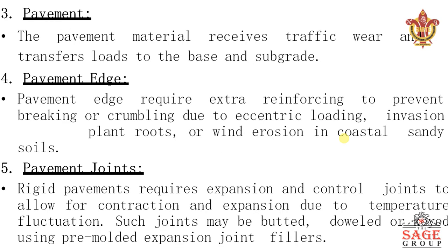The third is the pavement. The pavement material receives traffic wear and tear, and transfers load to the base and subgrade. Pavement edge. Pavement edges require extra reinforcing to prevent breaking or crumbling due to eccentric loading, invasion of plant roots, or wind erosion in coastal sandy soils.